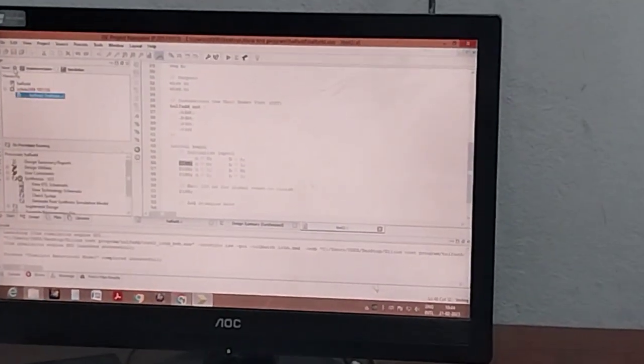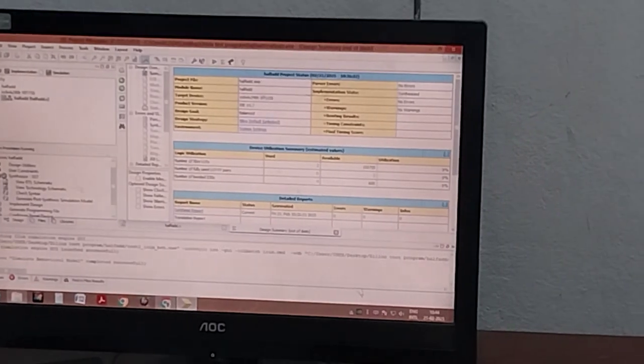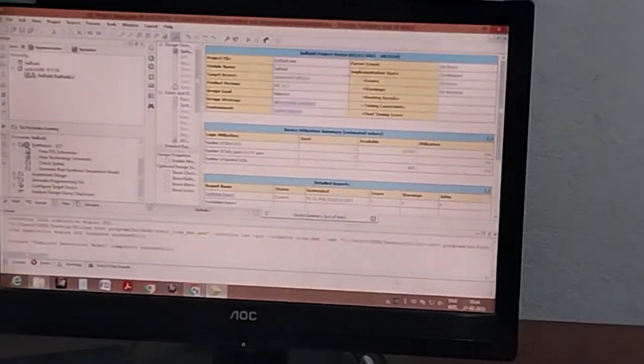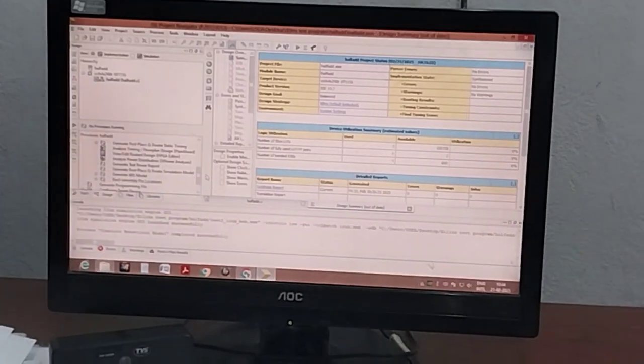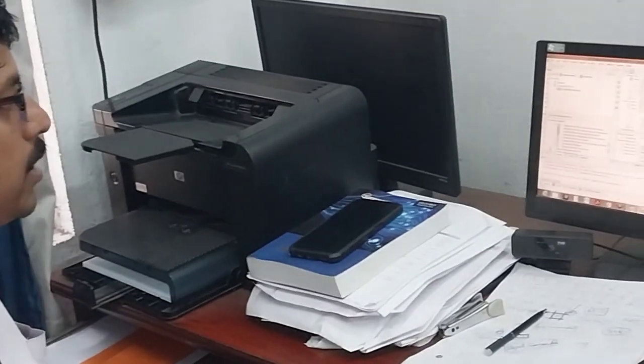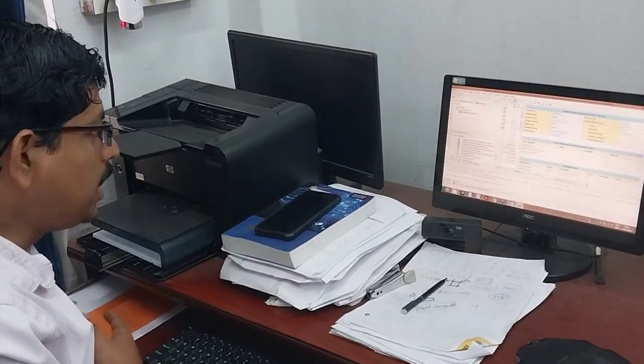If you go to the implementation mode again, you can also check there are a lot of tools under the implementation design. You will see that place and route is also there. In our design we have found the information of area and delay, and now another thing is the power consumption, how much power my design is consuming. Yeah, this Xilinx also provides.